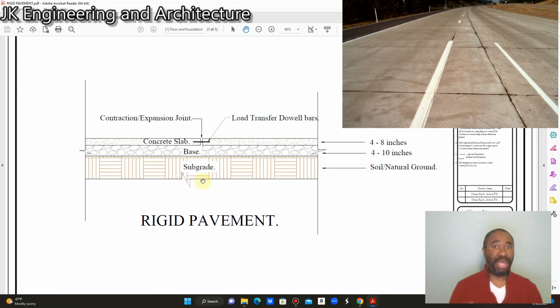But I also want to point out, based on my experience working on a bridge, when we do a concrete deck, a concrete surface always poses a lot of noise. So that is a negative when it comes to concrete pavement. The noise pollution is very heavy, and they always have to put up sound barriers along the corridor to cut down on the noise pollution, especially at night, when sound travels more because there is less sound to cancel out the sound from the pavement. So that is also a point I want to make, that the noise pollution from the concrete is very high, and oftentimes we have to put up a wall as a sound barrier to limit the noise from being transmitted all over the environment, where it is going to disturb schools, hospitals, or even people in their own homes.